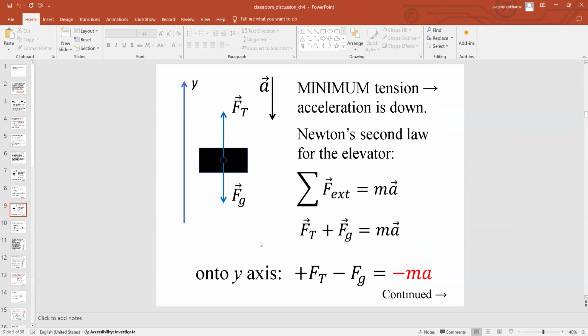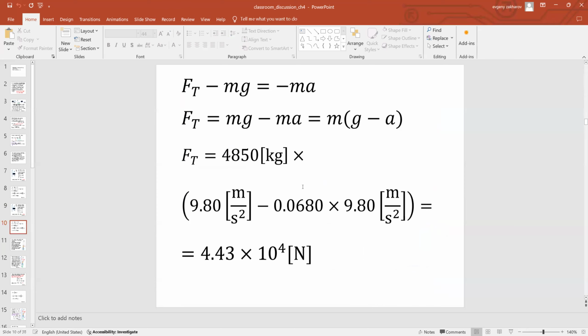So once again, draw a good sketch, show all forces, show the acceleration, show the F equals ma, represent all the forces, then do the components onto certain axis, so maybe both x and y axis. Keep in mind if it can be plus or a minus, and then just solve for what's missing.